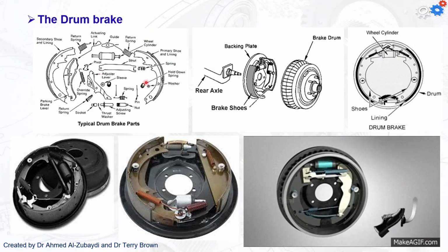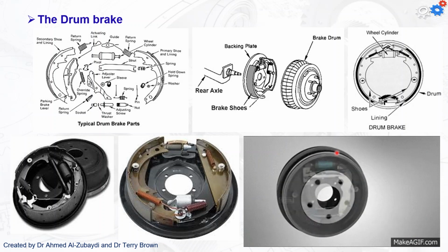Okay, so this is often called a drum brake, typical on the rear brakes of older cars. You still see them on some cars these days. Also trailer brakes, you'll see drum brakes like this. So yeah, push your foot on the pedal. Hydraulic force pushes the two drums apart. When you take your foot off, the spring here brings them back together and draws the shoes away from the drum.